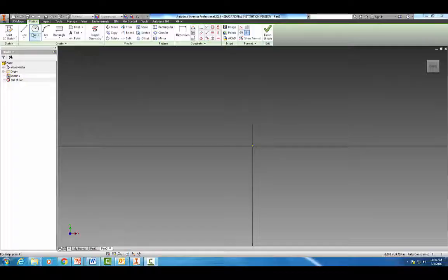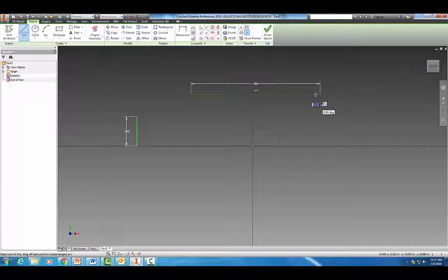All right, so the first thing I'm going to do is make two lines for scale. These are not part of our drawing. Okay, I'm going to make one about 0.2 in height, and then I'm going to also make one about 0.88 in length here. Okay, these are just for reference to help us build our drawing to scale. So let's grab our line tool, find your origin, and I'm just going to start making that basic 2D outline shape.